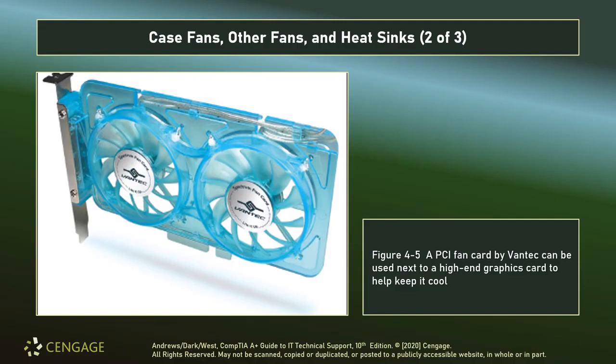There are some that are a little bit more aggressive in terms of their fan output. And they'll maybe be 3 fans long instead of just 2, or maybe they'll use a cluster of smaller fans in order to regulate heat over a potentially hot spot, if you will. If all the heat is centered on the back half of the card closest to the I/O shield, maybe there will be 4 smaller fans there that can spin at a higher rate of speed or lower rate to amortize power consumption. I've seen some really interesting configurations for this.